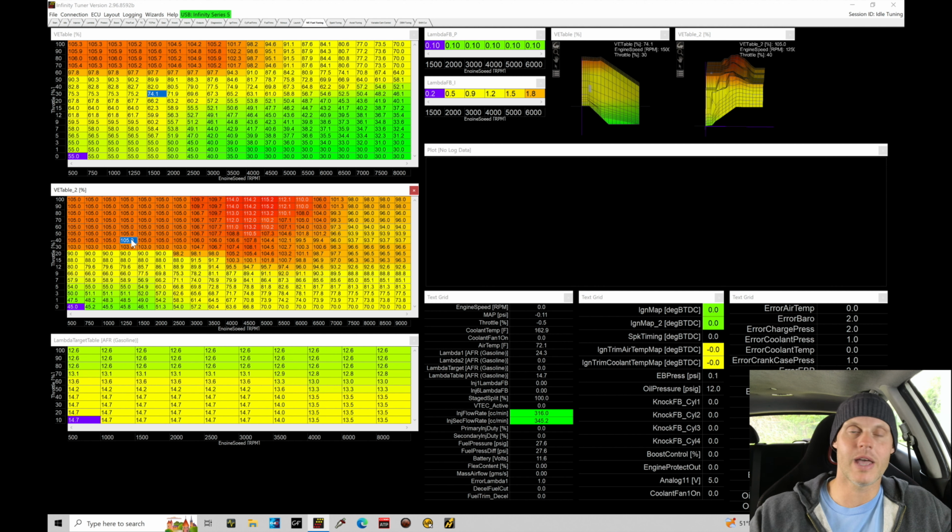There's always a low cam and a high cam because we have two distinct profiles with our cam. As we have low and high cam, or non-VTEC and VTEC, we're going to find two different airflow amounts and therefore two different VE profiles for our engine. And it's almost acting like two different engines. That's why we have these two different VE tables. So I always like to separate them. I like to calibrate low cam first, calibrate high cam next.